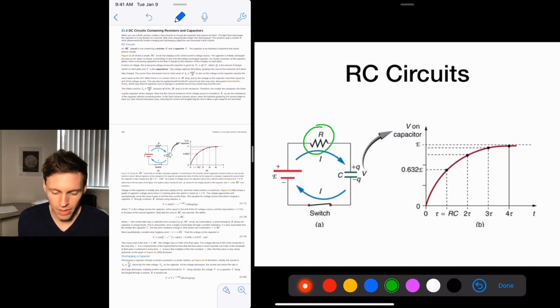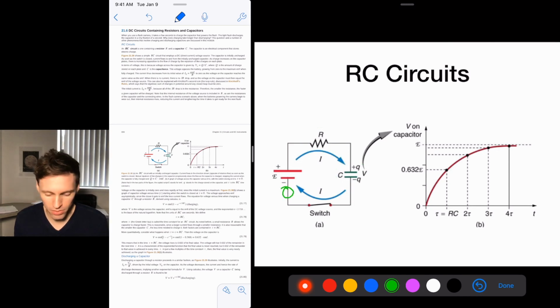So this is it. You've got a resistor and a capacitor. They are in series. Okay, so you've got your EMF. Notice we're ignoring our internal resistance now because we're not talking about it. So we just have our EMF, and then we have one resistor, and then we've got the current flowing in here, and here's our capacitor, and here's the voltage. It takes some time to charge. Okay, so your time constant, there's RC, 2 time constants, 3 time constants, 4 time constants, and then you're basically at full charge. Okay.